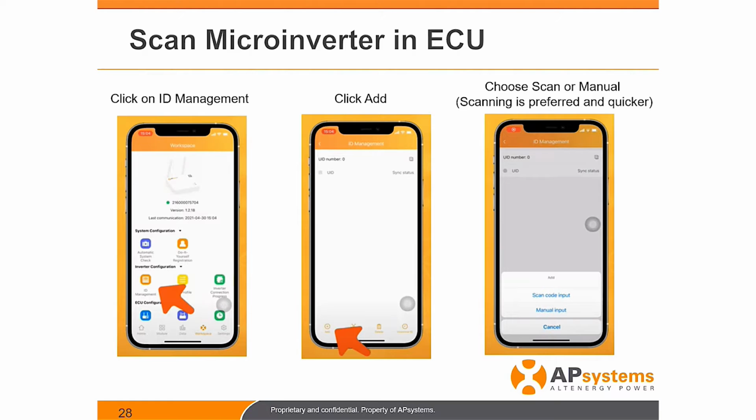Now, I'm going to take one step back. Every single microinverter, DS3s, or whichever brand that we sell, there will always be 2 serial stickers on the microinverter. When the installers go on the roof to install the microinverters, they're supposed to peel off one of the stickers and stick it on a piece of paper or piece of cardboard on the layout of their panel layout. Whether using knee maps or pylon, it doesn't matter. You generally want to print that, and then peel the serials and stick them on those panels where you've installed them.